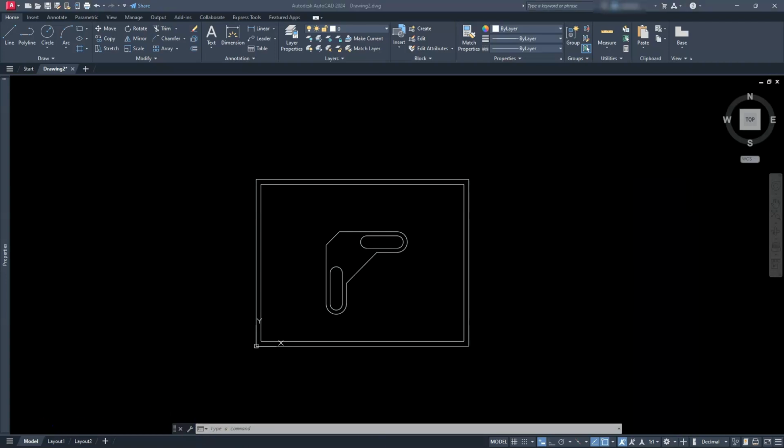Let's see if I can pull up a pen to show you what I'm talking about. If I have something set at a 1, let's put the 2 colons here, and it's set to a 20, and once again, my handwriting may be a little bad when I'm drawing this, but I have a 1 to 20. If you think about it this way, you probably won't mess up too much. I take the number on the right side, and that's my numerator, and then I divide it by the number on the left side, and that's my denominator, right? So that leaves me a scale of 20. If you pulled out your calculator and put in 20 divided by 1, you should get 20. Likewise with any other number.